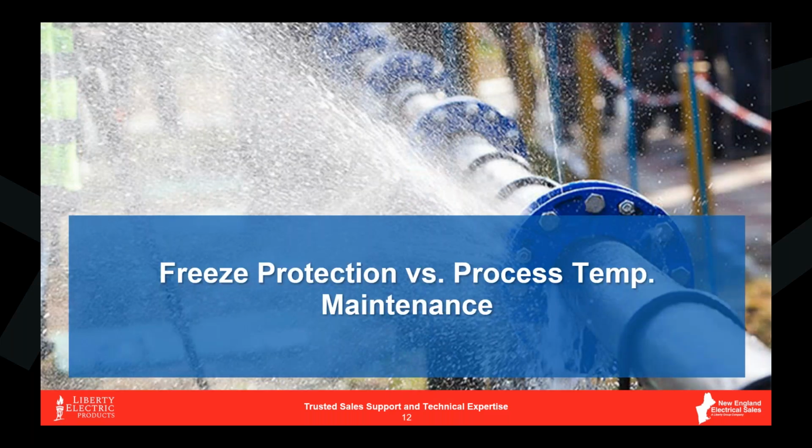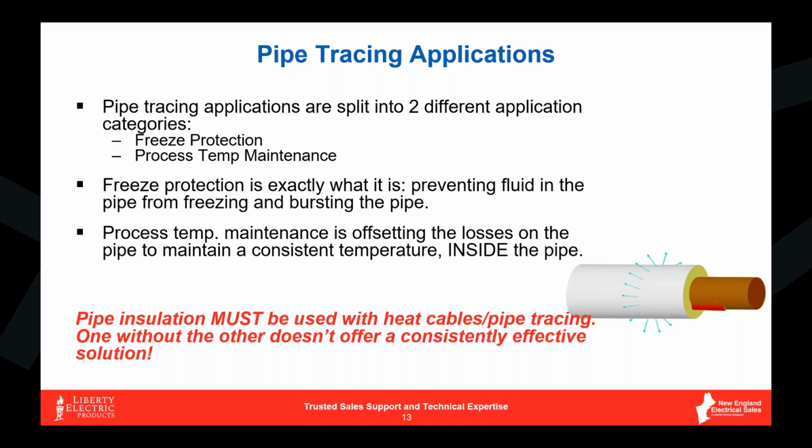So we'll talk about the fun stuff now and get into these applications. The two biggest applications you're going to find with pipe tracing are freeze protection and process temperature maintenance. The difference between these is, freeze protection is exactly what it describes, right? All we're trying to do is keep water or whatever is in that pipe liquefied and keep it from solidifying and bursting that pipe.